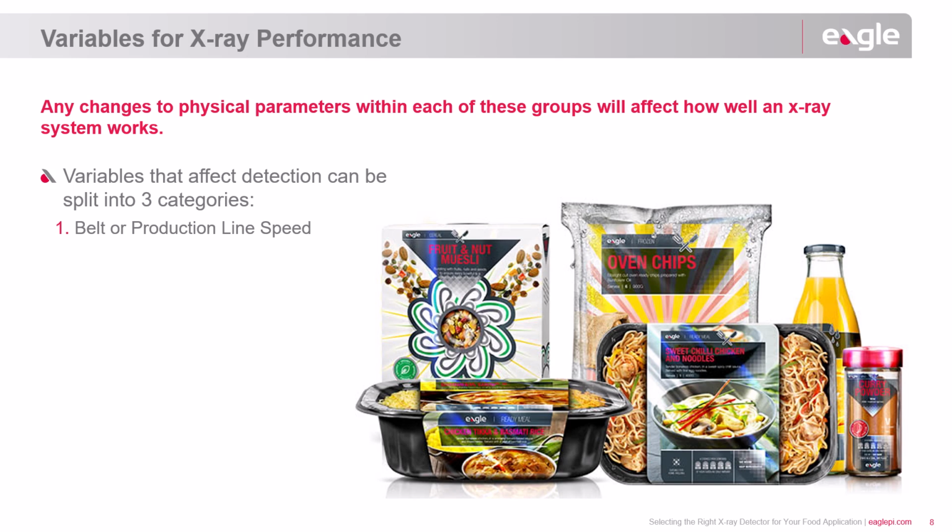The materials your product is made of, known as product composition, greatly affect how well the X-ray inspection works. Different materials absorb X-rays differently, which impacts the system's ability to detect foreign objects. Knowing your product's makeup allows you to adjust the X-ray settings for the best detection results.